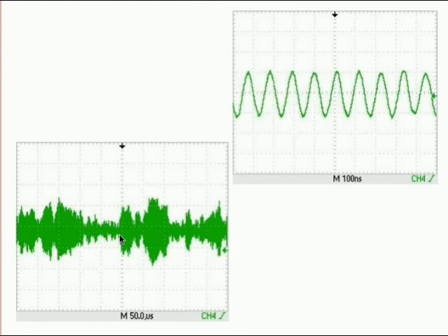Normally an oscillator wouldn't do anything like this, of course. The amplitude would be stable on an oscilloscope, no matter what time frame you look over. We can't see this is exactly 20 dB per decade, but we can see that with a linear oscillator the very close-in amplitude does fluctuate in the way that the close-in phase noise does.